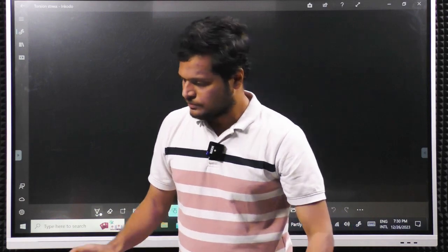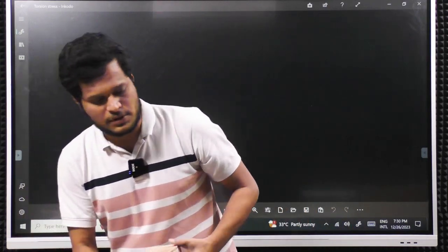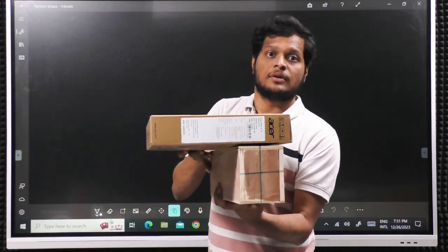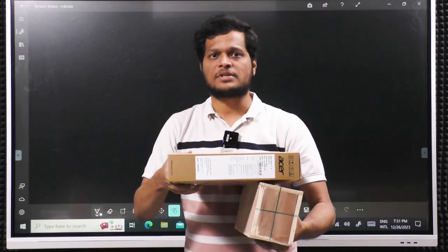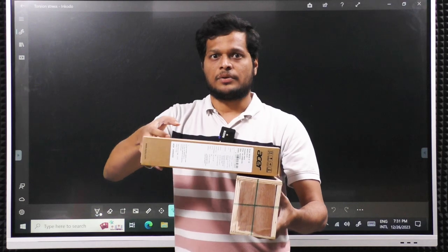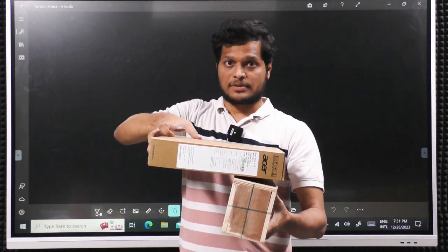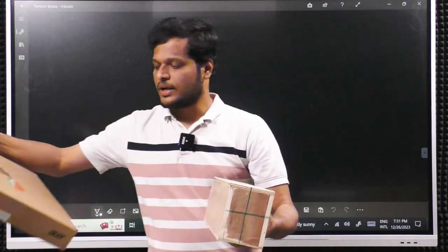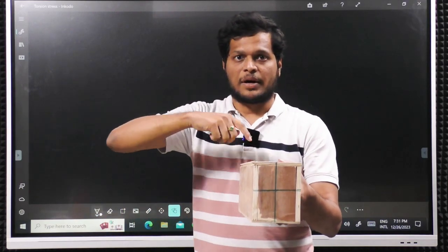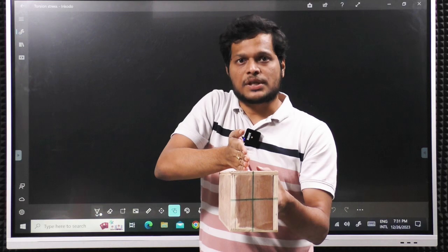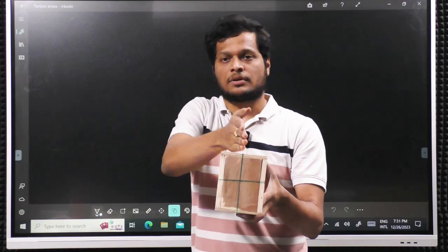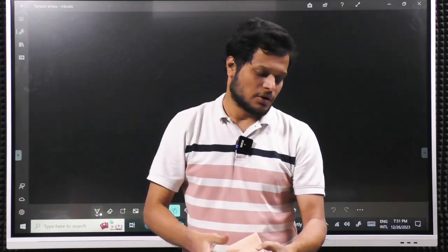Okay, now suppose if you see a cantilever beam like this, you can assume this as some canopy slab. For canopy slab you are applying a load on the slab on the top, right? So if you are applying the load on the top somewhere at the center, because for entire slab the load will be acting somewhere at the center, right? You can see previously whatever the slab I have shown you, the load will be acting somewhere here which is away from the longitudinal axis I told you, even if you just move your load slightly away from the center, you will get twist. Now the load is somewhere here, obviously it will create torsion. So canopy beams and cantilever beams where you have balconies, that also will be subjected to torsion.